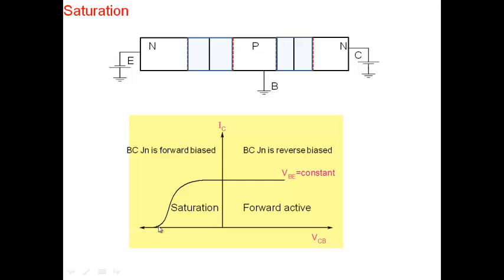So first we see that when you bias collector base junction in the forward bias, initially it remains constant, and the reason is that initially the collector base voltage is small. If you have a PN junction and you apply 0.2 volt, it means that it is forward bias in principle, but the voltage is not enough. You're not injecting enough carriers. So that's why there's not much effect on the characteristics. It's only when you make the base collector junction sufficiently forward bias, which may vary from transistor to transistor, it may be 0.5 volts or 0.4 volt, then you begin to see the effects here.